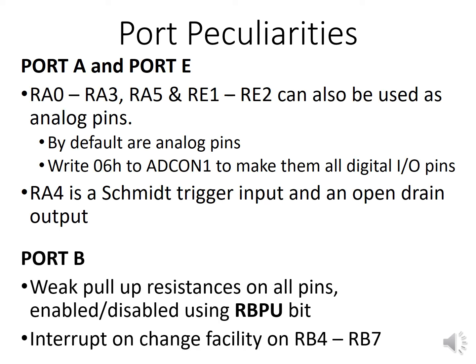Port B. All the pins on port B have weak pull-up resistances. These resistances can be enabled or disabled in software. This is done using the bit RBPU in the OPTION register. So you may consider a suitable use of port B is connecting input devices that need